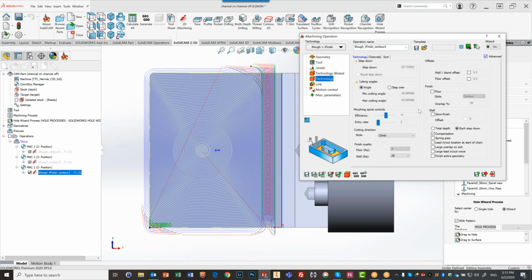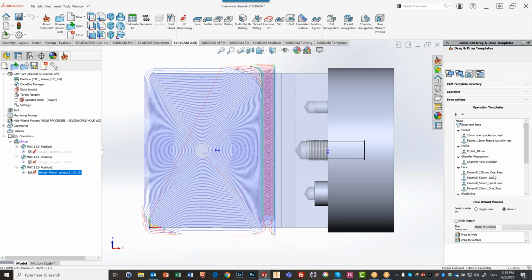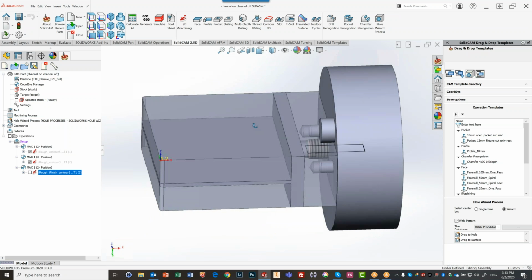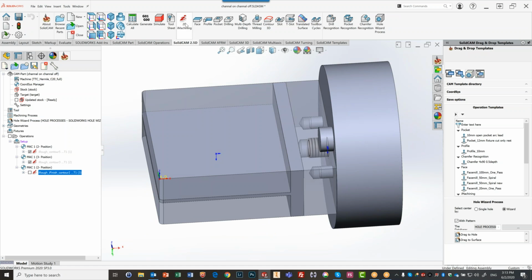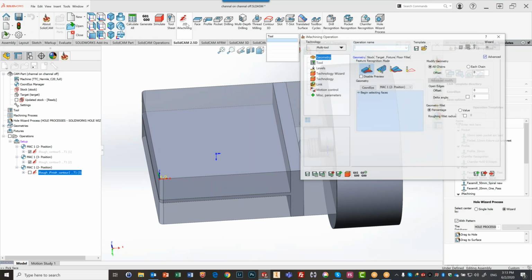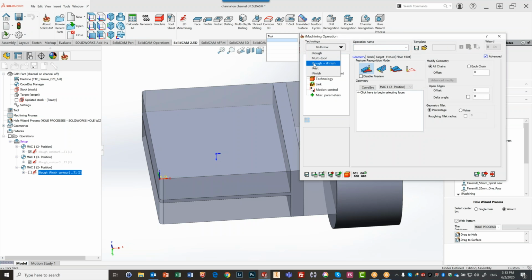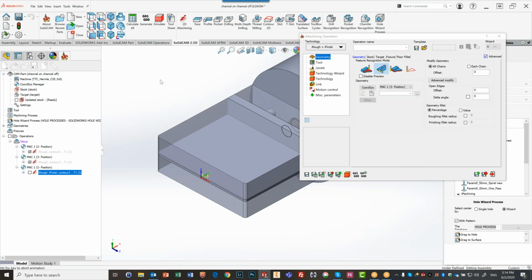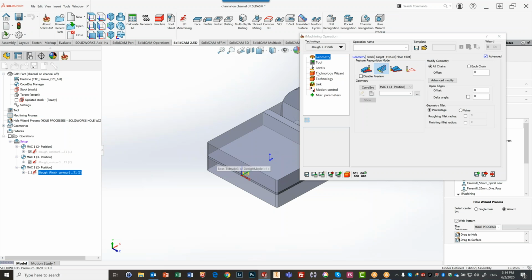Now that worked out fine. I want to do the flip side. So I'm going to take away the marks and create another iMachining operation. This time I'll use the same method as before, but I'm going to use Mac 1 position 3, because I'm clicking on my home position related to this side. If I click over here, you can see this is the side that it's going to machine.